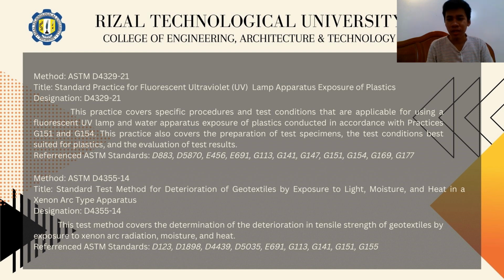The ability of a plastic material to resist deterioration caused by exposure to light, heat, and water is a property of significance in many applications. This practice is intended to induce property changes associated with end-use conditions, including the effect of ultraviolet solar irradiance, moisture, and heat. The exposure used in this practice is not intended to simulate the deterioration caused by localized weather phenomena such as atmospheric pollution, biological attack, and saltwater exposure.